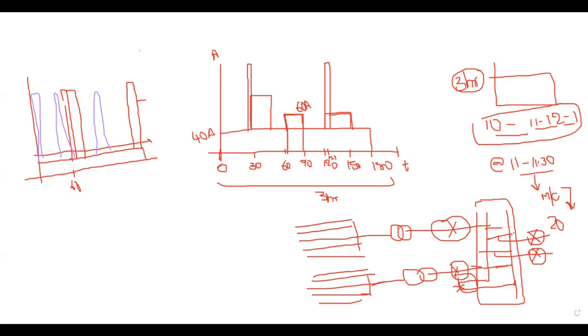After preparing the duty cycle, you will come to know that in the first half an hour, the battery should have the capability to feed, suppose, 30 amps of current. After that, there is some intermediate load which exists for the next minute, so the battery again has to meet that requirement. And again, there is some non-continuous load.